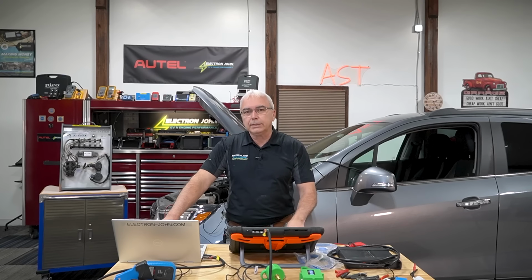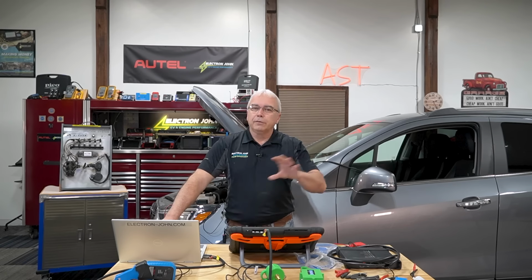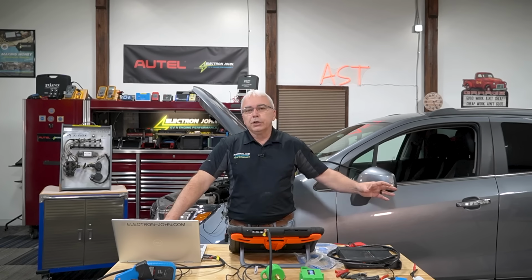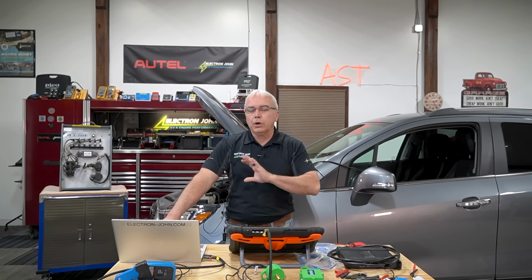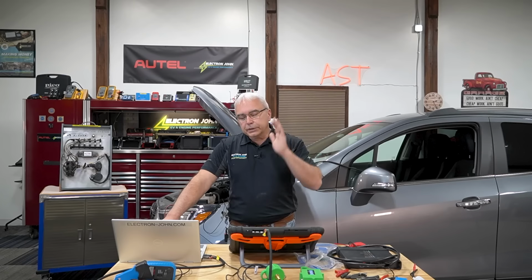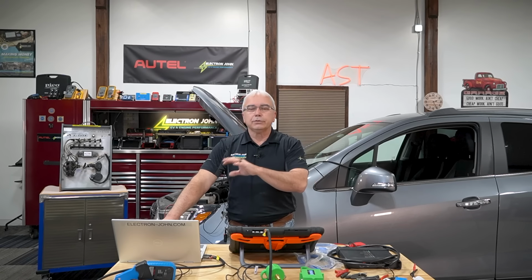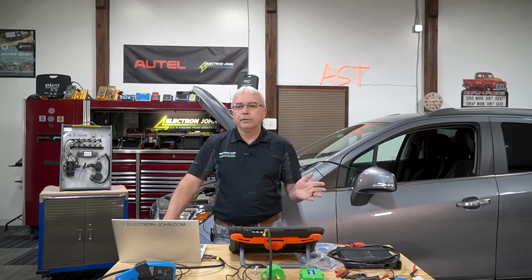But if all you did was fix that O2 sensor code, that drivability complaint is still going to be present because, again, the computer wasn't looking at that for that drivability condition. So again, your information system is loaded with all kinds of different system strategies. Mode 6, there's a ton of training classes that I've done over the years.